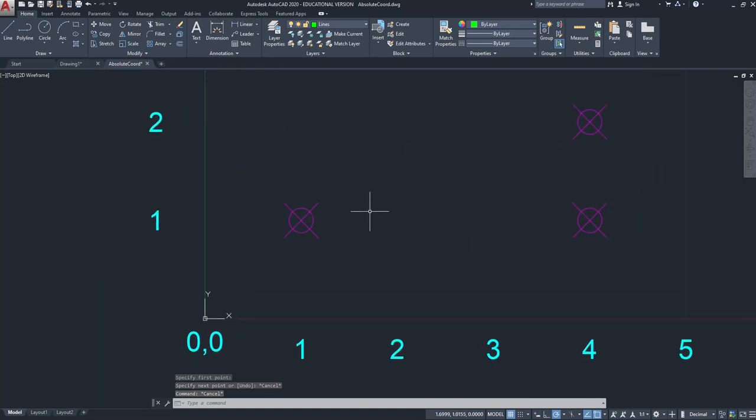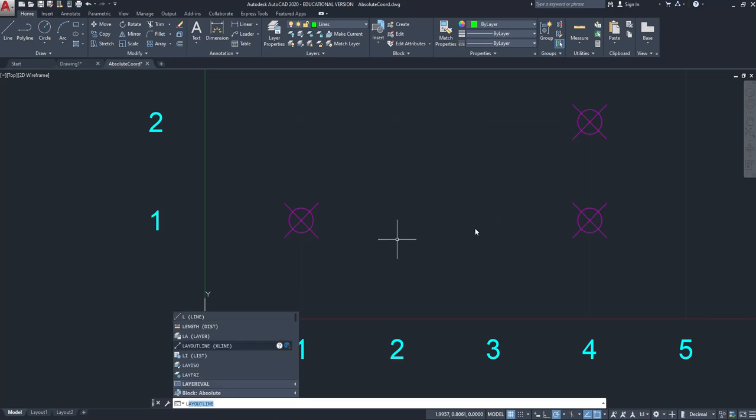Okay. So I'm going to enter that first point again using absolute coordinates, and just a reminder, absolute coordinates are measured from the origin. So I'm going to click on line. I could also initiate the line command by typing L enter. It's a shortcut, L enter. Enter initiates a command. So if I type L, you see down here at the command line, it pops up. I'm inputting at the command line with the keyboard, or I can come up here and click on an icon.